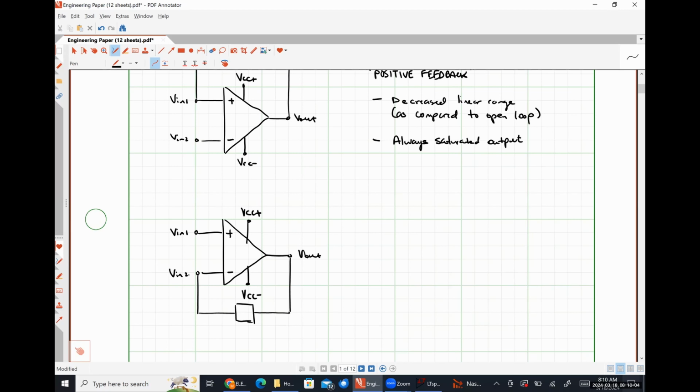And so effectively in a situation like this, instead of the output being added to the input, causing the output of the system to gradually push towards saturation, now we're taking away a piece of the output from the input signal and dragging that output signal down to some stable operating point. That's the role of negative feedback, right? So in a negative feedback system, we have a significantly increased linear range.